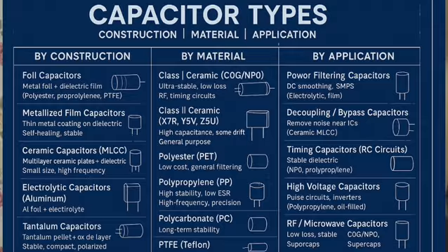The ceramic capacitor is called MLCC, multi-layer ceramic, with plates plus a dielectric; it is small in size and high frequency. Electrolytic capacitors widely use an electrolyte. The tantalum capacitor is made up of tantalum pellets plus an oxide layer; it is stable, compact, and polarized.